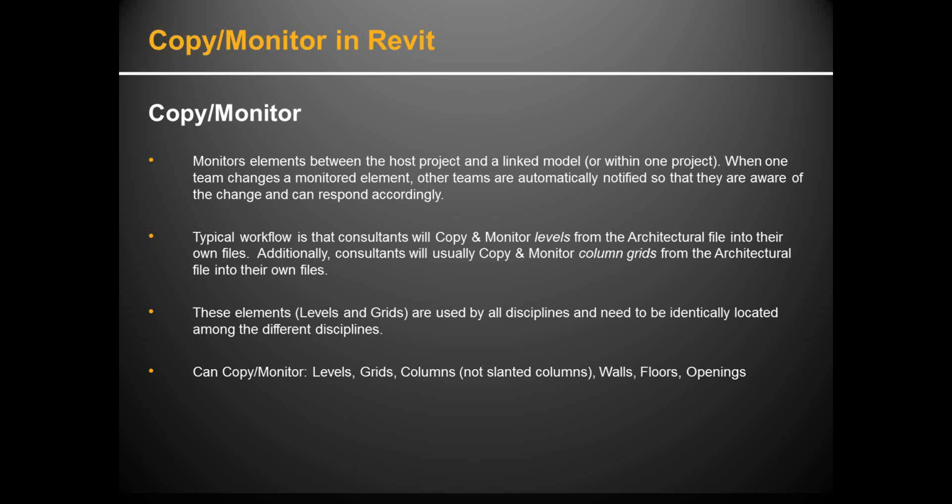The typical workflow is that consultants will copy monitor the levels from the architecture file into their own files. That is almost universal. Additionally, the engineers can copy and monitor the column grids, the grid lines, from the architecture file, or if the structural designer is in charge of the columns, they may have ownership of the column grids. And we can certainly copy and monitor column grids from the structural Revit file.